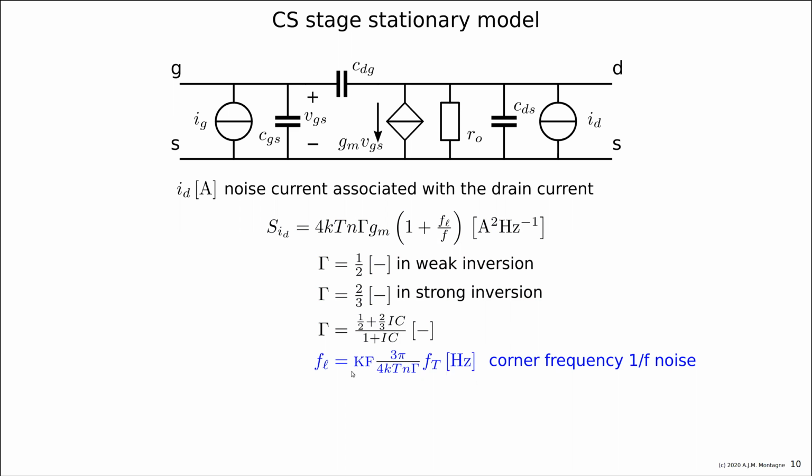And this is especially interesting because it covers the design problem for the active antenna that we are going to do, because maybe some of you already looked at the specification for this active antenna, and then you might have discovered that there was more noise allowed at low frequencies than at high frequencies. And one of the sources of this extra low frequency noise might be this 1 over f noise. And there you have a design criterion for this corner frequency.